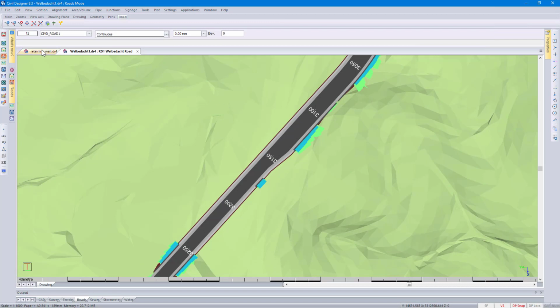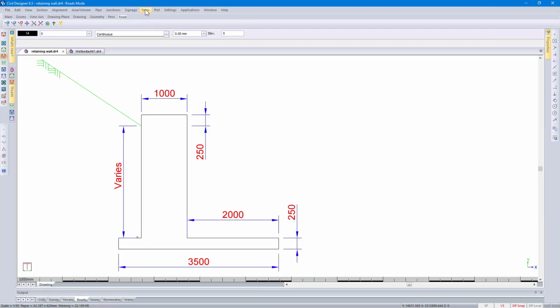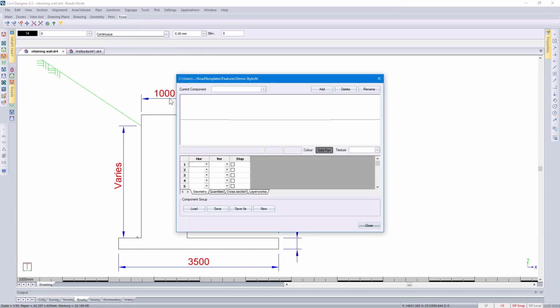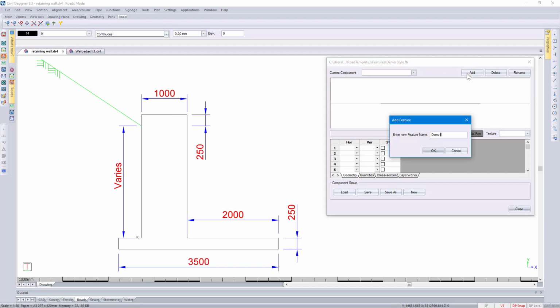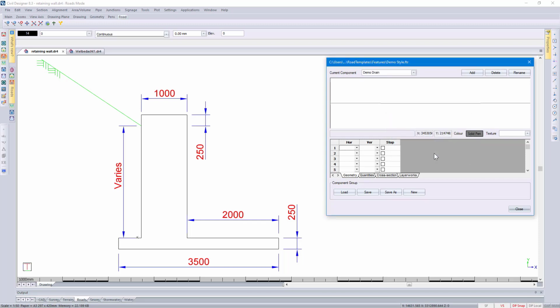I'm going to change my diagram. I'm going to Tools and selecting Component Editor. Let's add our own components. Looking at a very basic example, I'm going to specify the horizontal and vertical dimensions. I'm specifying a negative because I want my line to go down. So this being my start point and that being the end point. If you use your coordinates over here, you can see we've horizontally moved to the right-hand side 600 mils and we move down 300 mils.